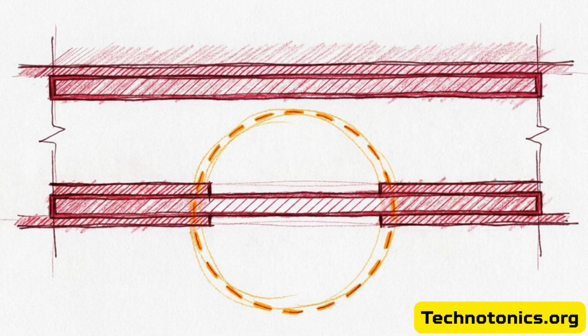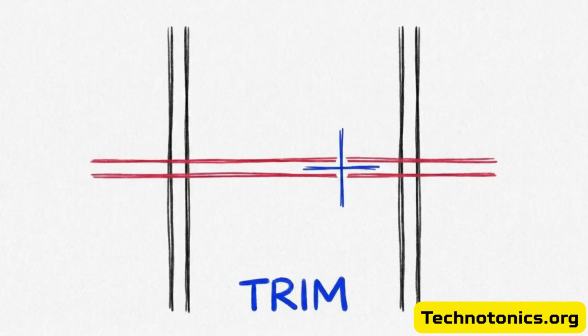Now we need a way to walk into this room. Type L for the line command and draw 2 intersecting boundaries straight through that solid wall to define a doorway. To clear a space between those lines, we use a destructive tool, the trim command, by typing TR.